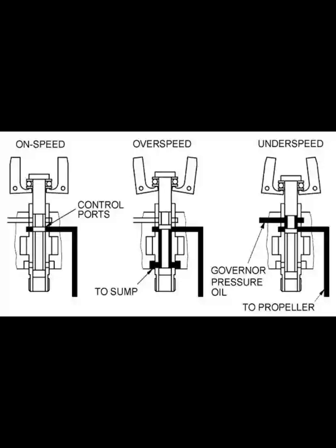What should you adjust if a pilot requires 50 more RPMs on an aircraft equipped with a constant speed propeller? Adjust the governor's prop lever set screw. What adjustments are powerplant mechanics allowed to make to the prop governor? Only the maximum RPM stop.